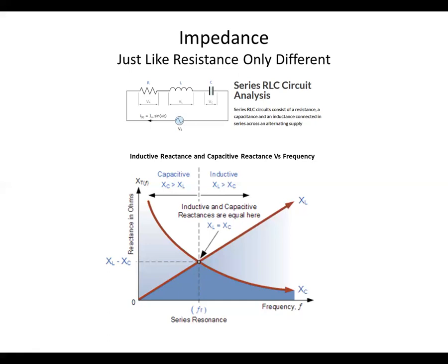They say, well, I'm driving my SWR down. And no, you really aren't. What you're doing is adjusting the resonant frequency to get it to where it'll operate better. You really don't adjust the SWR, you move the resonant point to get it where you want it.